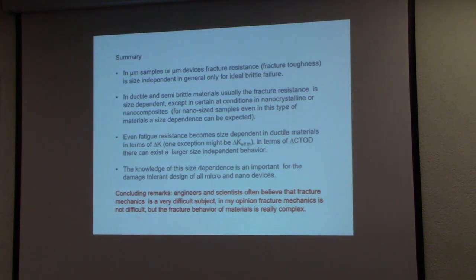All the time, when we come to the difficulties, then we have to look: oh, the fracture process zone becomes so large. And it is not clear what is crack propagation when we have first maybe a small amount of blunting, then we have a formation of micro cracks, then the micro cracks coalesce with the main crack. How should we characterize it? Yes, we can characterize. If we have, for example, small-scale yielding condition, then we can say, okay, at this K this happens.